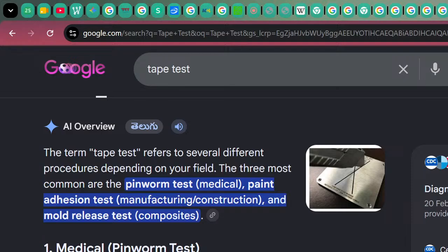Just like segmented, intermittent, flush or regular, and the other one, long-short or uneven. Keeping this aside, there is no topic allocated for gold fingers. Unfortunately, today we also discussed the ENIG procedure, which is not part of our curriculum. Usually in this curriculum, we only reveal that we use copper tracks. If you opt for the higher course, we will reveal that we use a combination of three materials: copper, nickel, and gold, and it is real gold. We will reveal the thicknesses in the higher sessions, but I gave you the information.